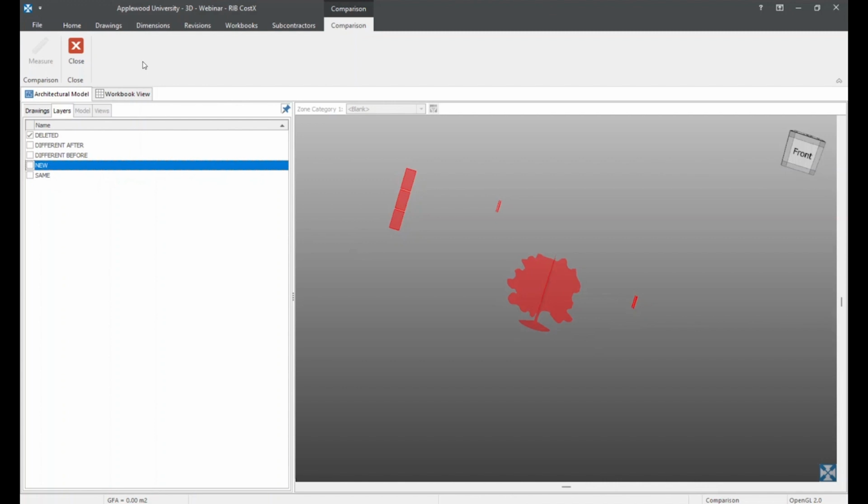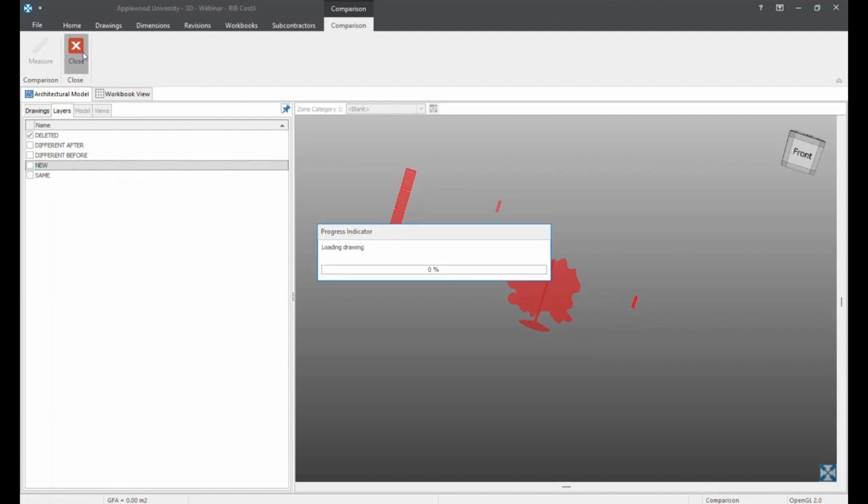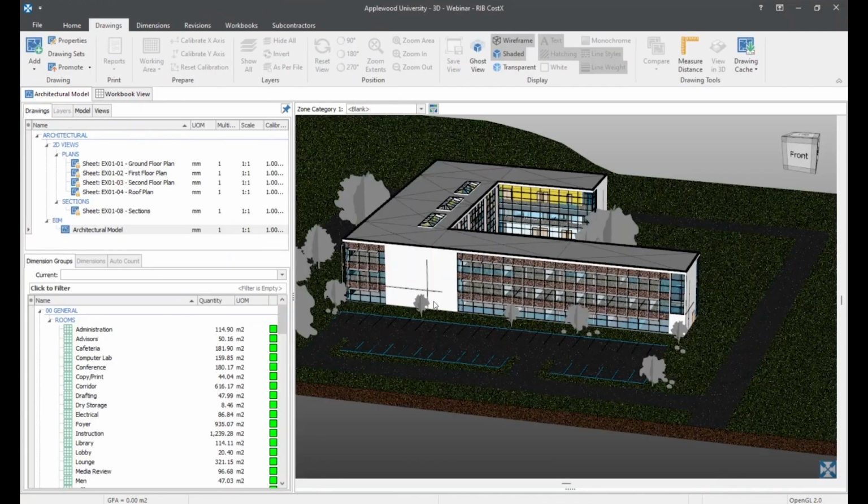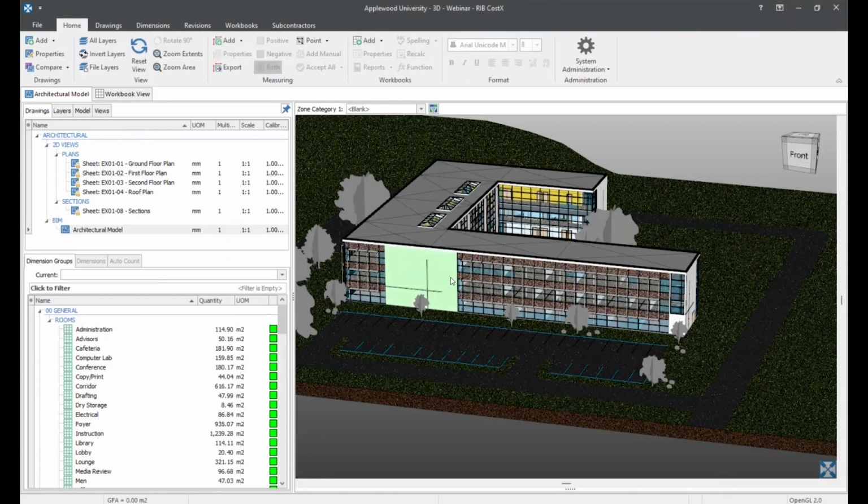Next step will be to import new dimensions. In our previous step, where we promoted the BIM dimensions, the changed and the deleted BIM dimensions have been automatically revised. However, if there are any new elements which have been newly added, they have to be imported. So in this particular example, we had previously used model maps to extract the quantities. So we are going to continue extracting the quantities using the model maps method. This basically helps maintain consistency and efficiency in updating the estimate.